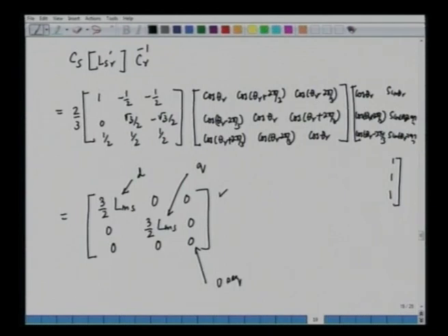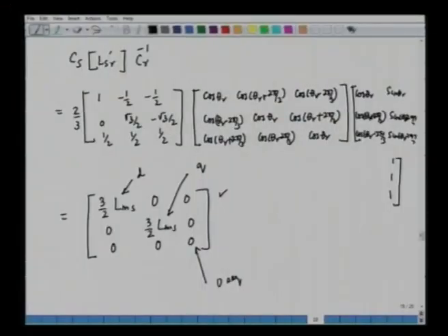So, this is obviously coming because of the transformation, and in the dq model we have seen that the inductances are not a function of the rotor position, that is, independent of theta r. So, with this background we can write down the equation of the induction machine in a stationary reference frame or in the stator reference frame.